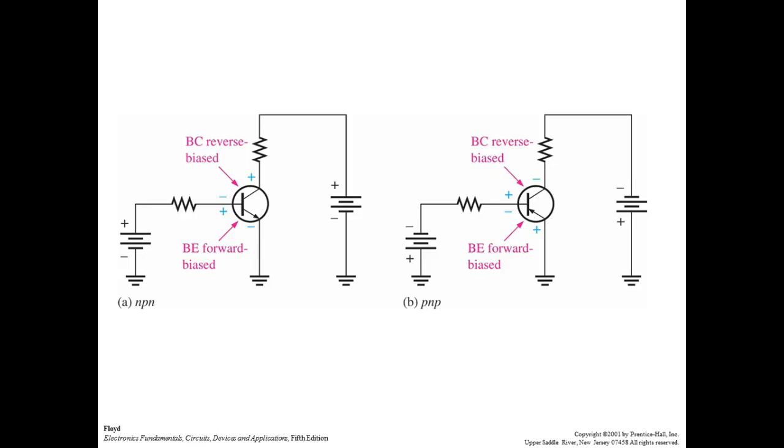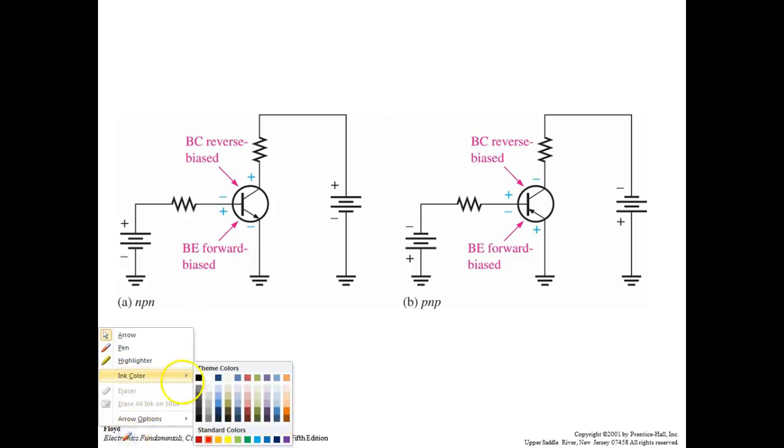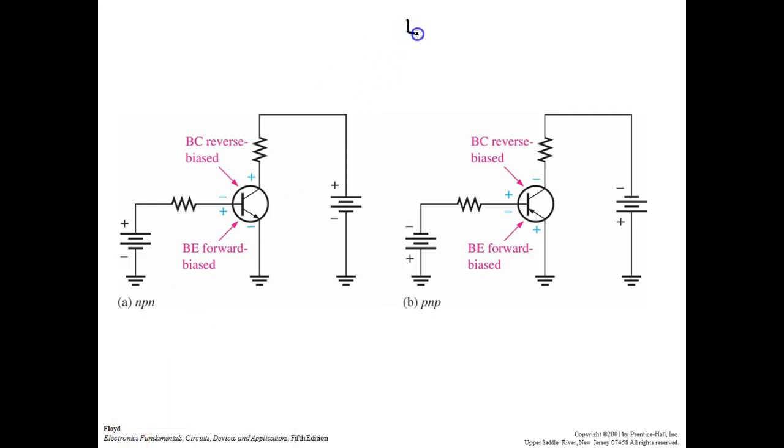So what that means is, if I wire it correctly, I can hook it across the source. I'm going to use DC, but it could just as well be AC, and then make this common. Then we take this thing called a wiper and hook this to a meter.